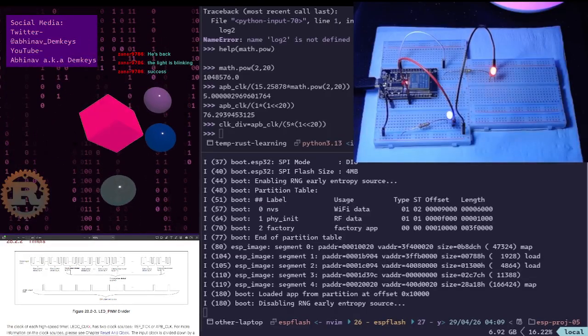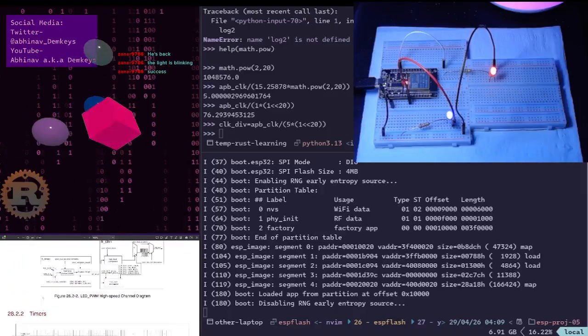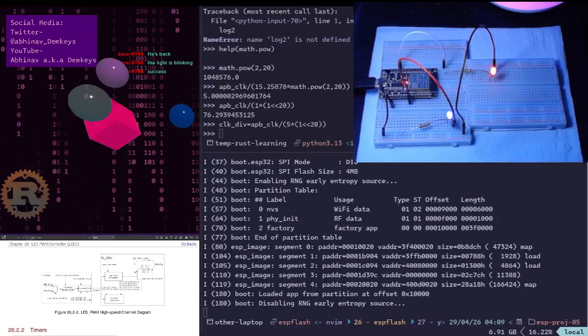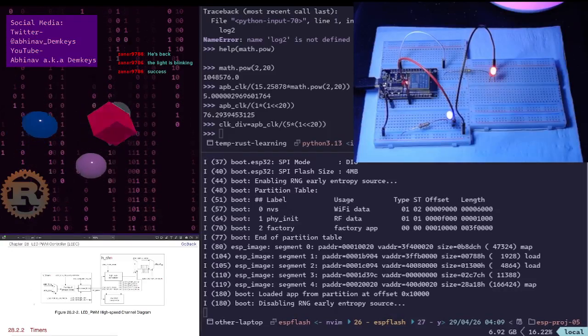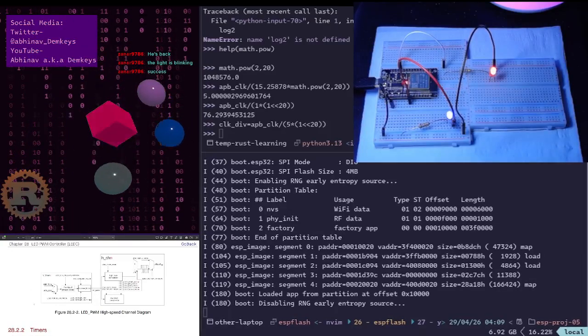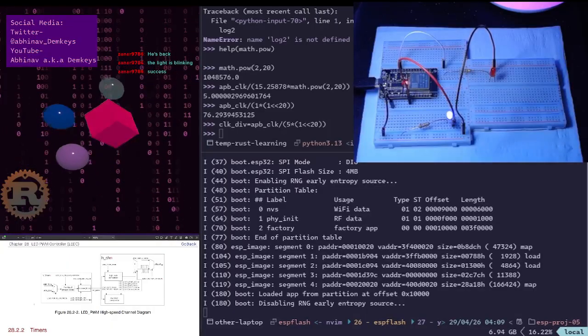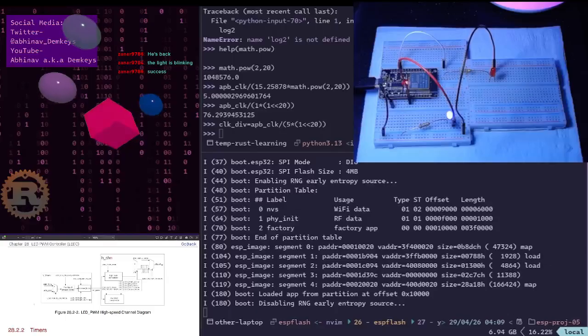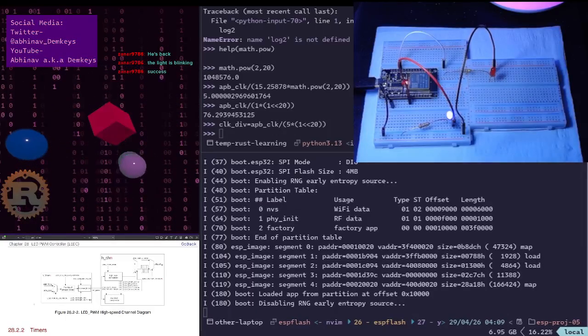So every n number of pulses, it allows one pulse to go through, and that one pulse goes into the counter and increments the counter. And the counter is set up so that it's a 20-bit counter. If we use a 20-bit resolution, it's going to let the counter go up to 1,040 something thousand, and once it hits the max value there, it's going to reset the counter.